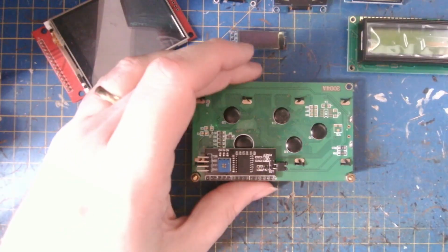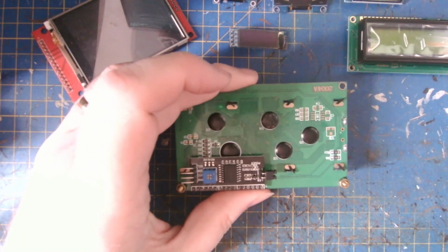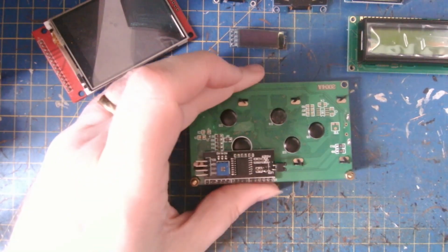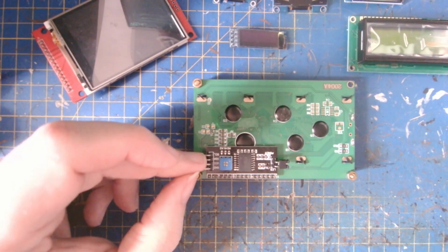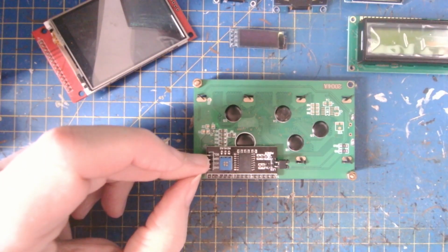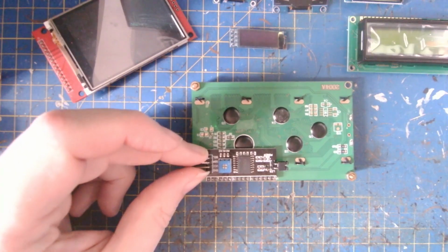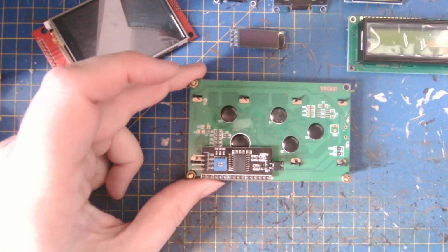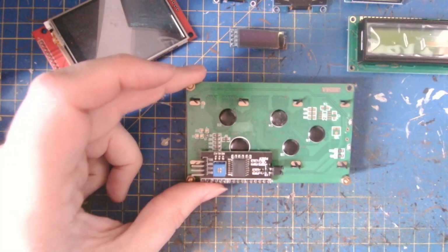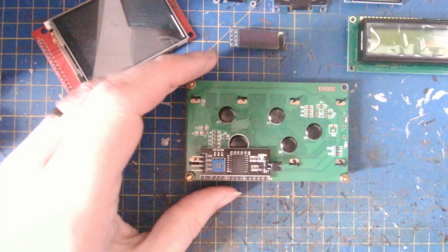It's not as fast. This is in the kilohertz speed range, 100 kilohertz, 200 kilohertz. Bit less computationally intensive. It's 2 pins. Because the speed is slower, the electrical interference characteristics are a bit different. It's designed to talk to simple things that don't need vast amounts of data sending to them. You can get sensors, keypads, light output things. There's all sorts of stuff you can do with this.